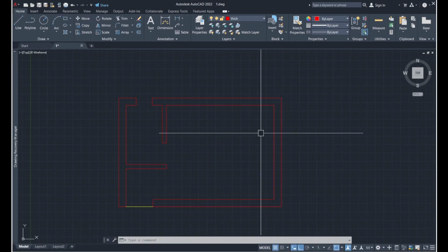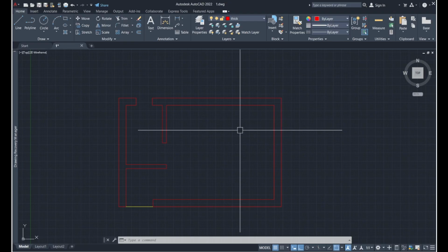So now let's add some windows to the living area. Before we do that, we'd like to discuss that generally when we draw a plan, the section plane is cut at around 1 meter, but this is really up to you. You could imagine cutting it at 1.1 meters or 1.2 meters.